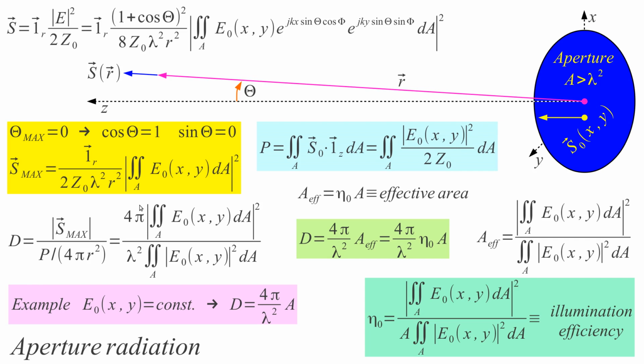The directivity of an aperture, you see here, can be made arbitrarily large by increasing A. By increasing A, I can increase the directivity. So I know the trick to increase the directivity, without doing many complex things, just this simple. How is this directivity increased? It is increased because these two terms actually narrow the radiated beam.